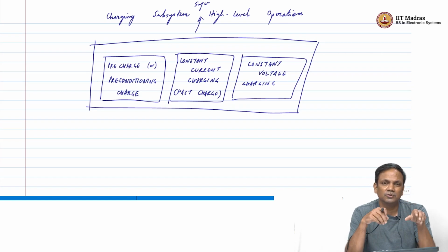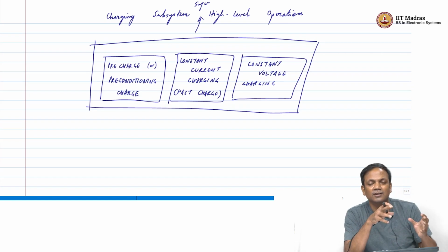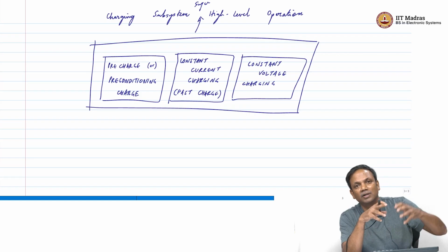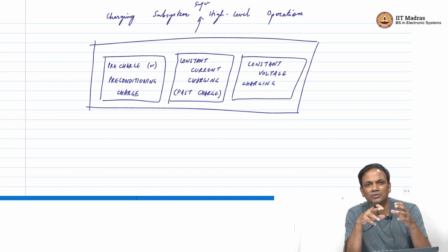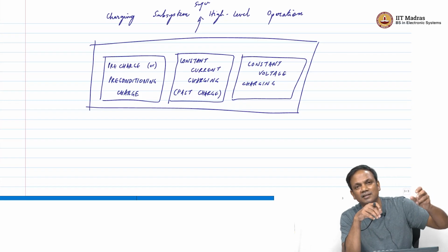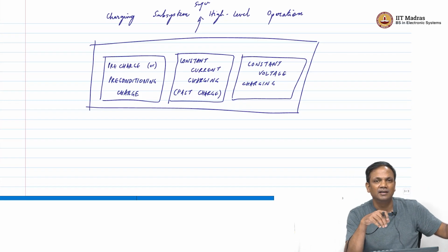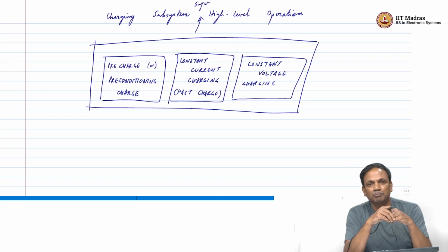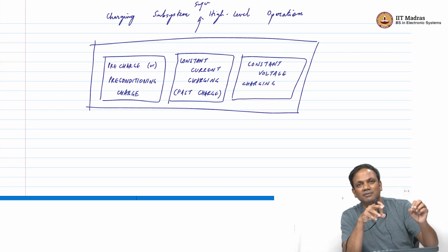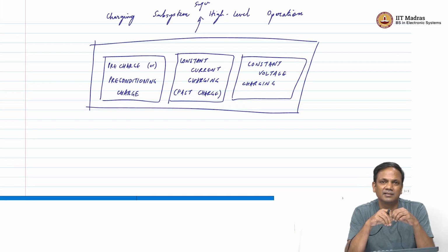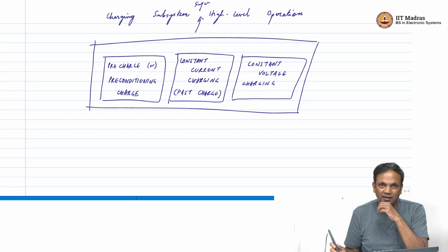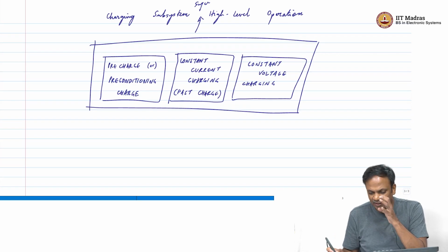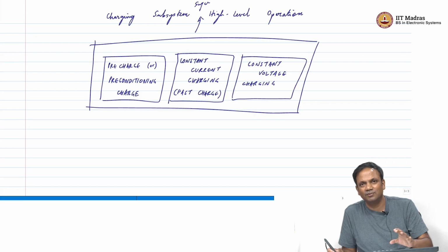So what you want to do is, until you get close to the battery voltage, dump large amounts of current to charge the battery, and once you get close enough, start slowly reducing the current so that the battery voltage will asymptotically approach the rated voltage. Right, that is what we want from the operation. So again, this is what we want.